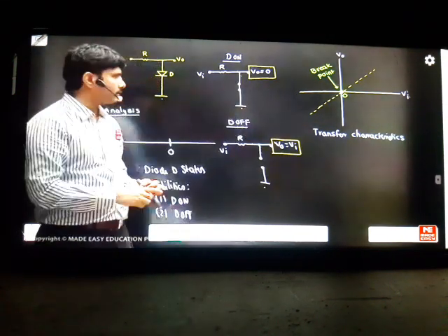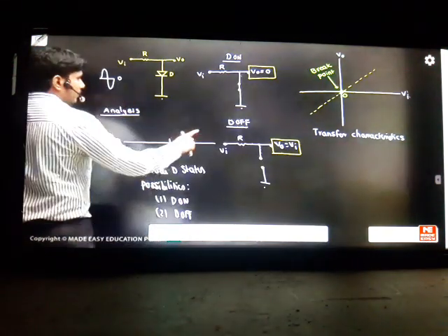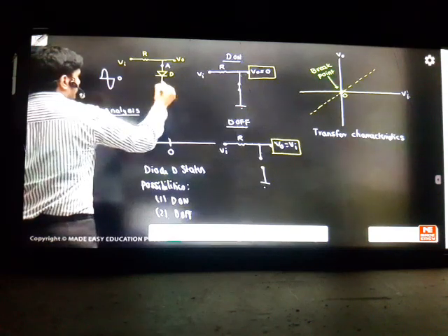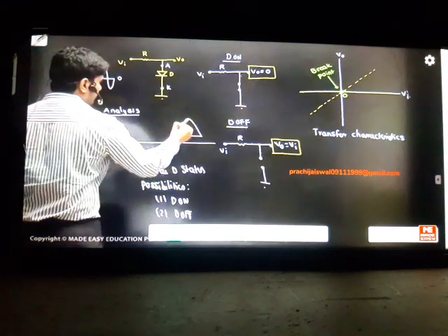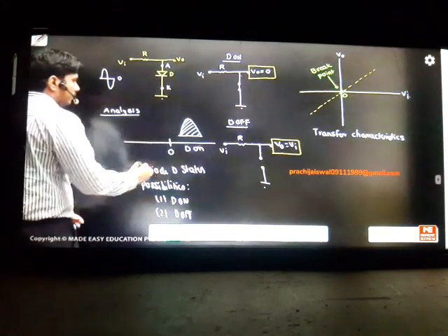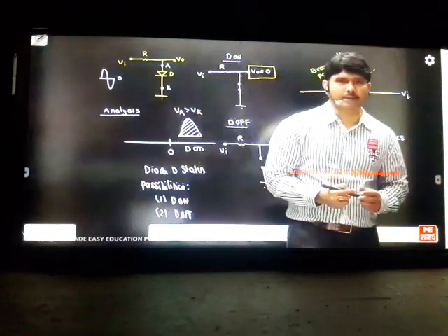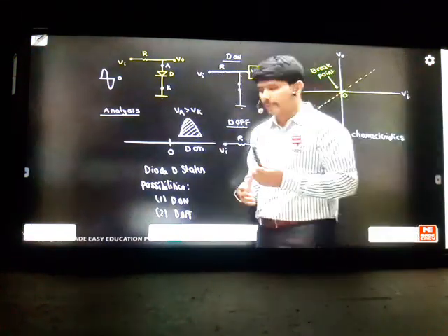Just find the intersection point. Now finally, an observation we have to do. What is the observation? Zero is confirmed here. Below zero, the signal is going towards the anode side and the cathode side is zero. Just apply the knowledge: anode is positive, cathode is zero, meaning positive cycle if you apply on this side. Can I say that the diode is getting on? Because in this case anode is greater than cathode. Whenever you give a positive signal on the anode side with reference zero, you're crossing zero, which means the diode is getting on. So we confirm that above zero the diode will be on.